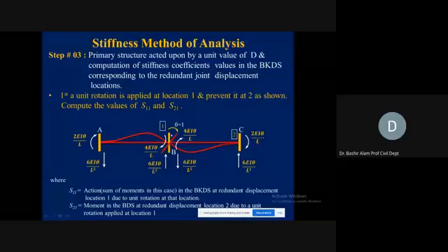Now, for the left span, if you want to put this in equilibrium, here we have 4EIθ divided by L, and at the left we have 2EIθ divided by L. So this will now cause rotation of the span. To put this in equilibrium, we need to balance this by the opposite couple. So how is the magnitude of the opposite couple calculated? It will be the summation of this unbalanced moment, which is 4 plus 2, so 6EIθ divided by L, divided by this span, which is L. So it will be equal to 6EIθ divided by L square. So this is the balancing couple.